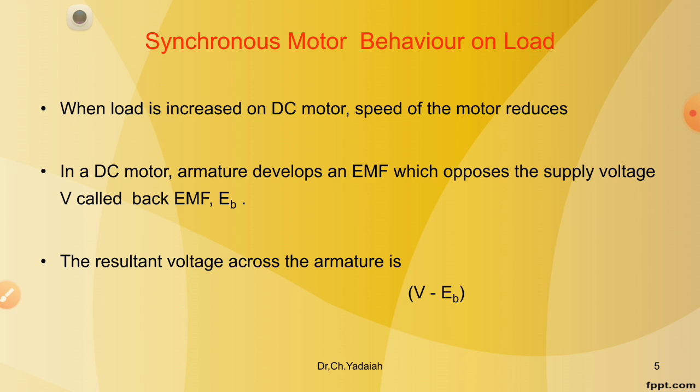That means if load is increased gradually, step by step, on a DC motor, we observe that the speed is gradually reduced. But in our synchronous motor, if load is increased gradually up to some extent, the speed is constant. That is the main significance of the synchronous motor.